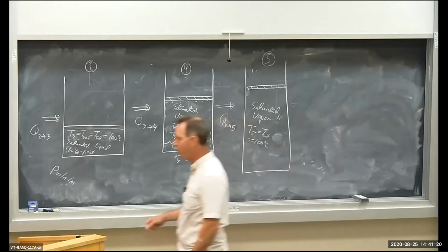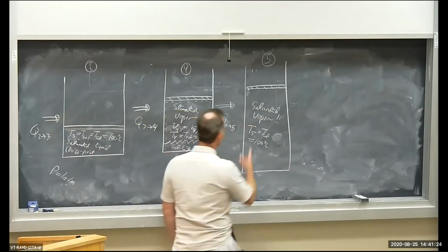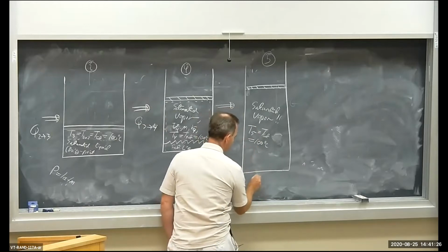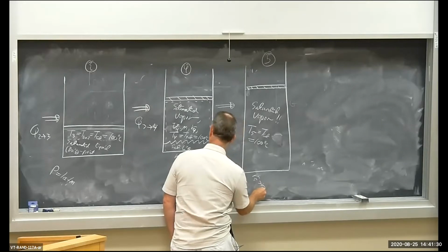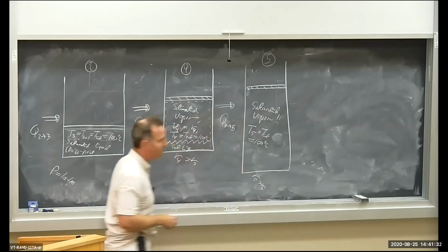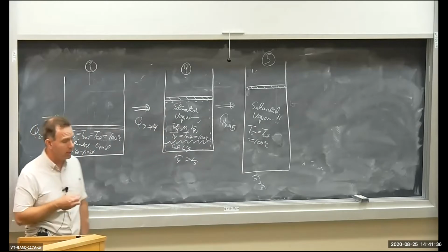T-saturation means boiling temperature, okay? And note that the piston has gone up, so the specific volume at state 5 is greater than the specific volume at state 4. So it's expanded more because we boiled away more of the liquid. We boiled away all of the liquid.